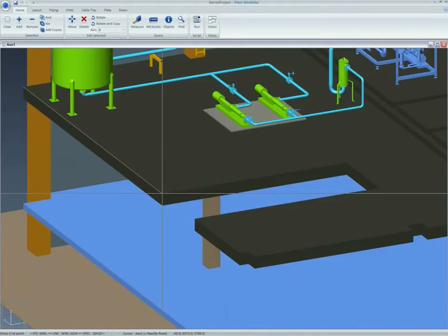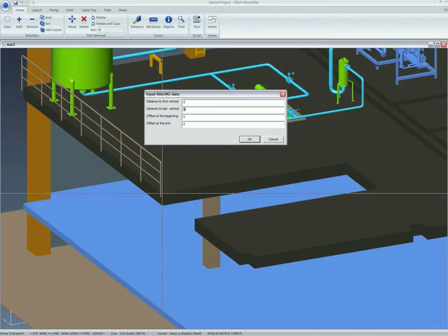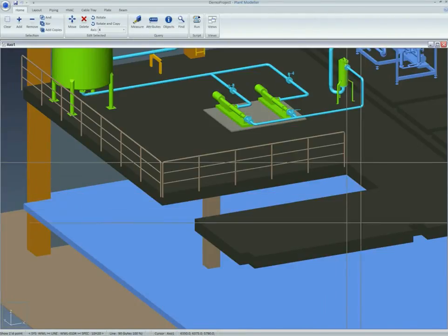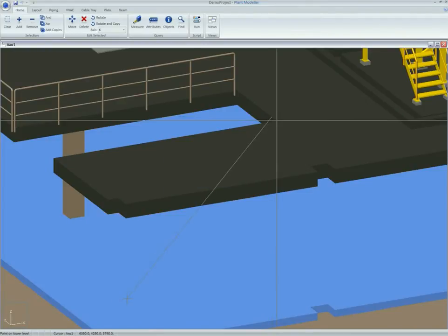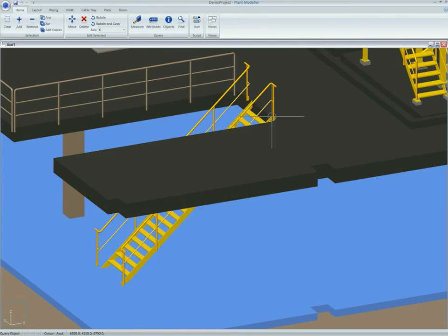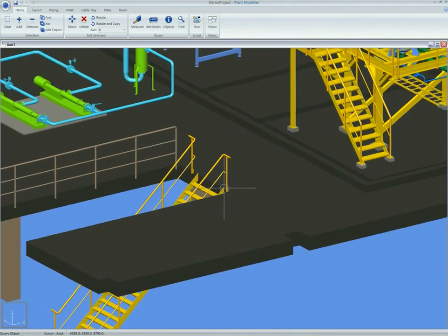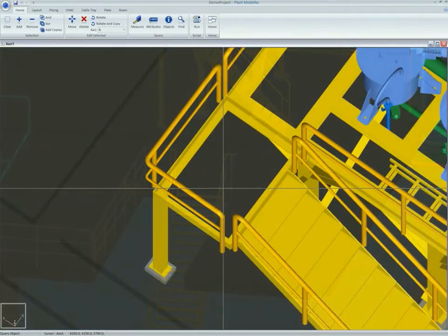Cadmatic has several functions for creating steel structures. The railing settings and the amount of vertical and horizontal pipes per meter are easily adjusted. Entire stair structures can be created with a few mouse clicks. Once the material specifications for railing sidebars and steel steps are defined, the software automatically creates the structure according to the given points in the model. Gratings and related settings are also easily created and adjusted.